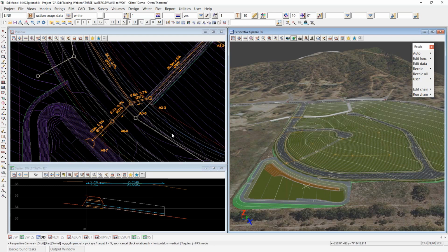So in that case, it's really an answer of having two different road design files and doing a bit of a switcheroo at the right point. It doesn't come up too often, that problem, but in dual carriageways it has. We have been looking at a proposal to support both a center string and a reference string, but at this stage it hasn't happened yet, so that would be the only solution I could offer.